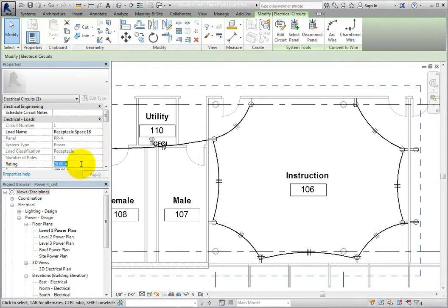First, I would recommend reading the wire sizing documentation on the Autodesk Wiki help site to better understand how Revit calculates these sizes. Then you can calculate the values needed to get the correct wire sizes, rather than guessing and checking. Also, you should look at the wiring settings in the electrical settings dialog.